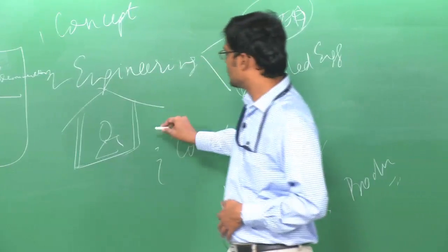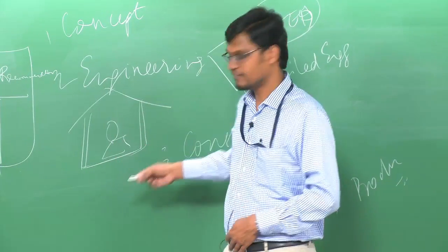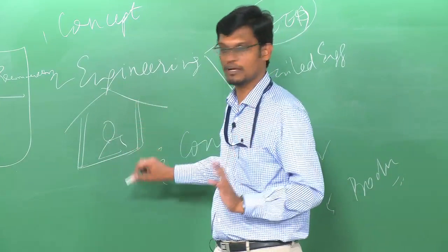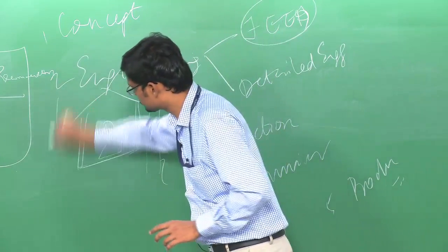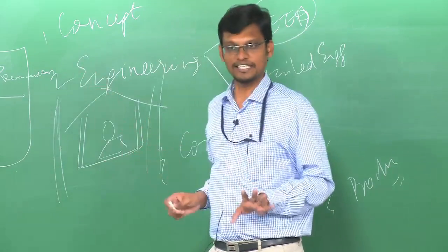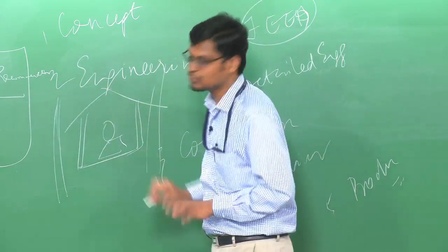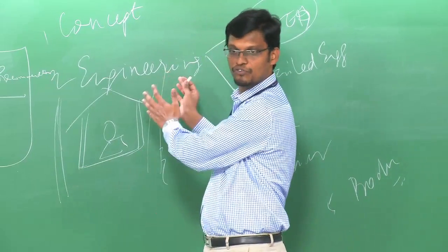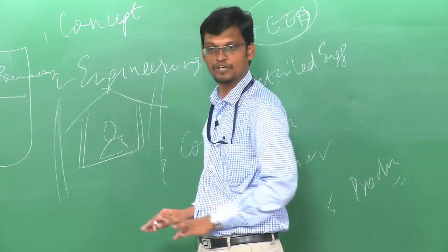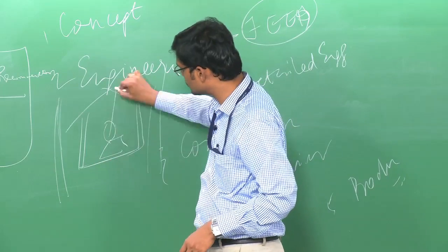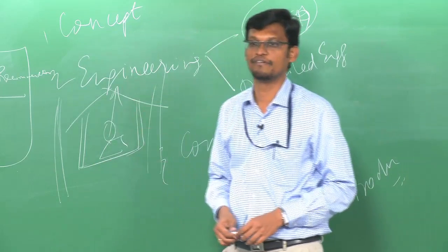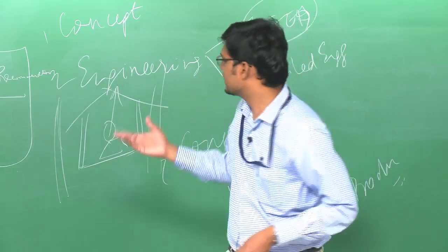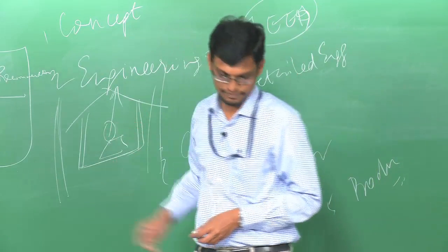See, I will give you an example. You go to process industries, you will find it very familiar. Like you have a big transfer pump installed, and all along it you will have equipment. Now, during the project stage, he would have happily installed this, because surrounding it you had a path to move and equipment to bring in and install. Tomorrow, if there is some repair and I want to remove this, how will you do it? That is an example of operability, maintainability, whatever.